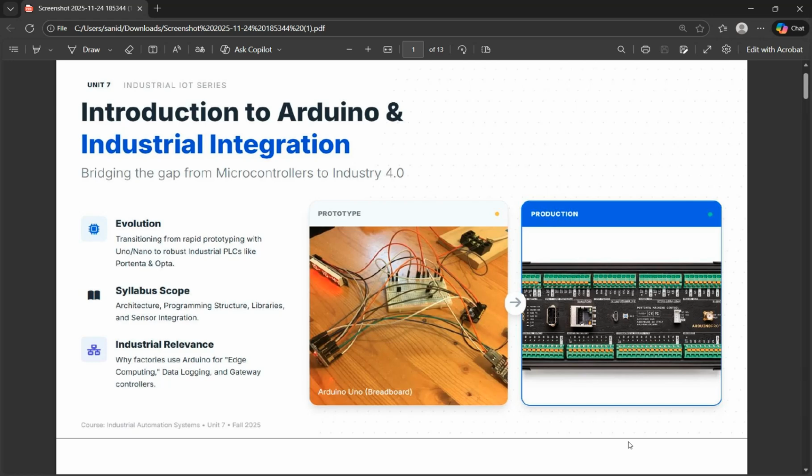Once it opens, the first thing we do is select the board we are using. Usually it's an Arduino Uno or Nano. These are the simplest boards. And then we choose the correct COM port. This configuration allows the code to be transferred into the board's microcontroller.